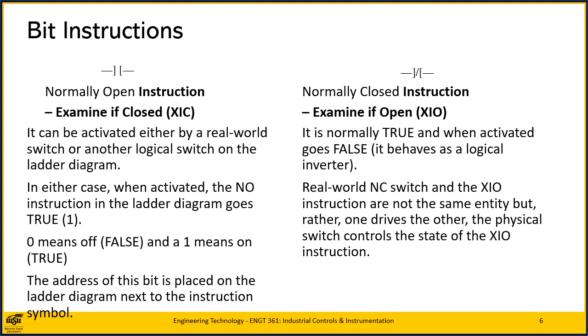To avoid this pitfall, remember that the real-world switch may drive the logical switch, but they are not the same thing. That is why you should use the terms examine if closed, shortened to XIC, for the normally open instruction, and examine if open, XIO, for the normally closed instruction.